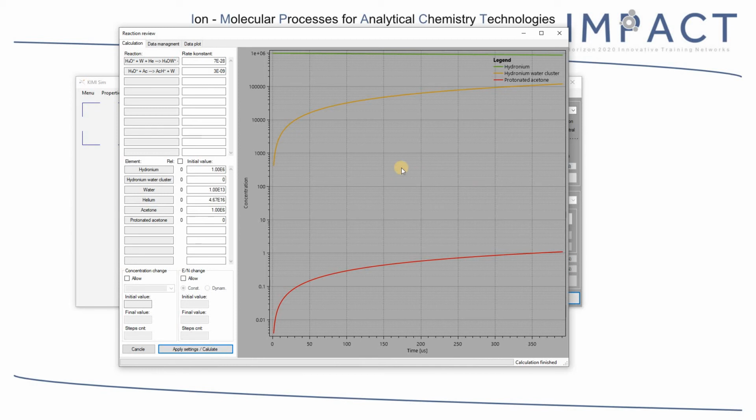If we are not interested in absolute values, but rather want to see relative values, we have this column of numbers here. Using this, we can specify the groups of particles that we want to use for a calculation of relative concentration. For example, we want to calculate the relative concentration of only ions. We will choose a different group for the ions, and clicking on the box, the program recalculates the values into relative ones based on the group selection.